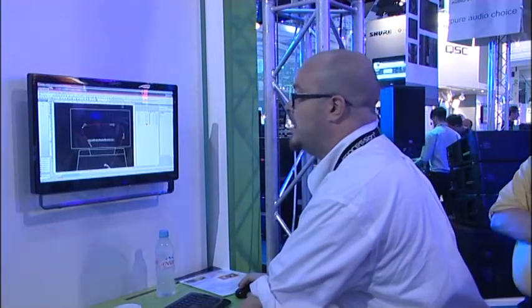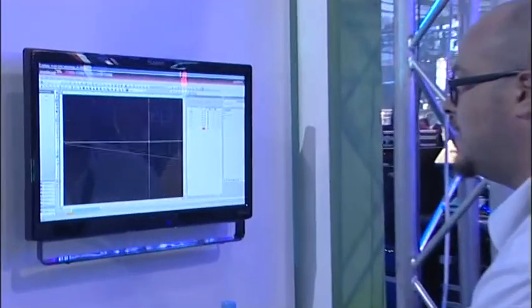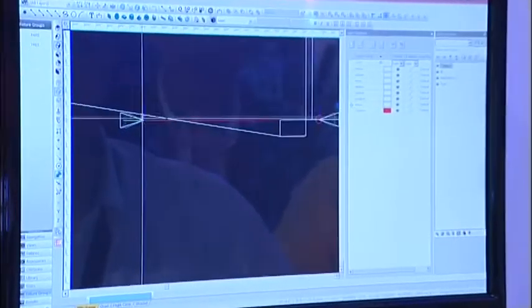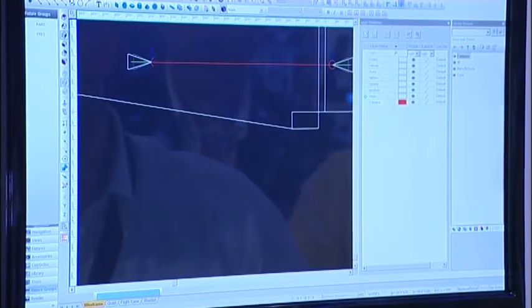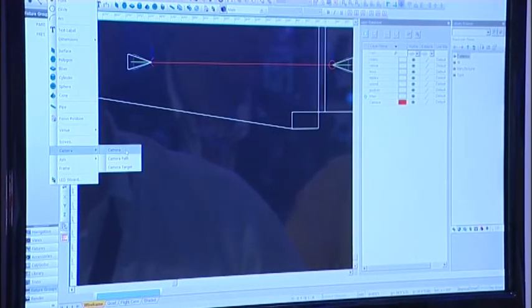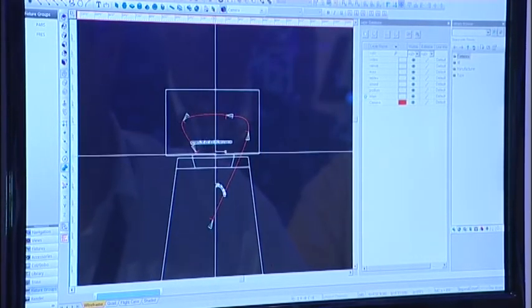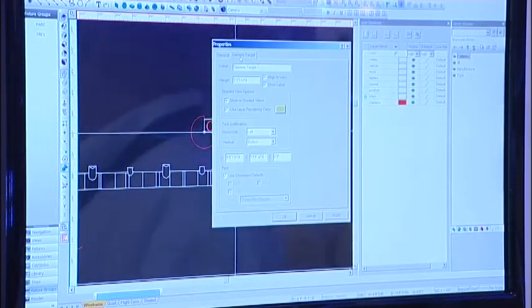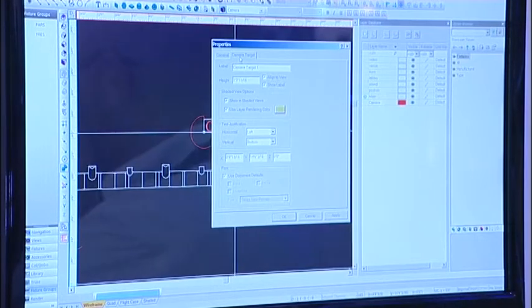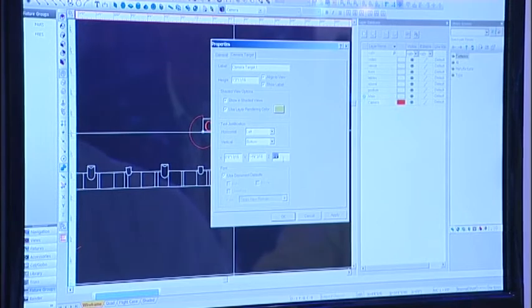Okay, if I go back into my design mode, let me go into front view, just make sure my camera path is, and it is not. Grab that, move it up. All right, I'm also going to draw what we have, a camera target. Camera target is exactly what you think it is. It is a camera target that you look at as you're moving around in your design. And what this gives you is the ability to have multiple focus points looking around as your camera is sweeping around the venue. I just want to make sure we give this height.